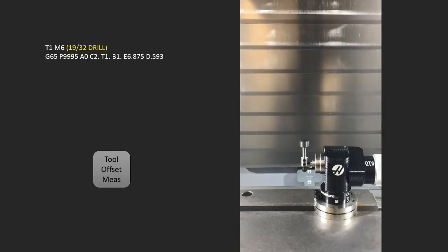So almost couldn't be easier here. And as I was putting this together, I was thinking about when I first started doing anything with the Haas machines, the tool offset measure was a really helpful tool at the machine because you could touch off with a shim or a gauge or something, and you would press tool offset measure, it would put your offset in, and then you could hit next tool and it would go up and index to the next tool and then load that and repeat.